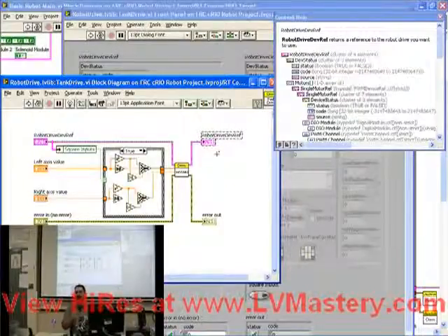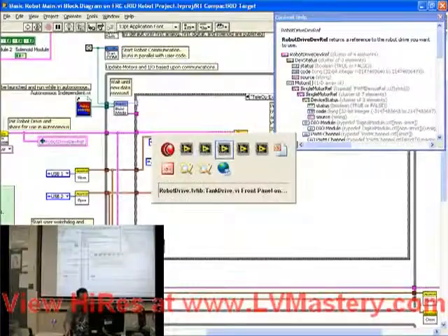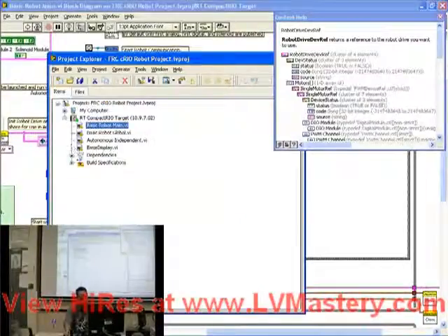Because what will happen, and I wouldn't be surprised if this happens a couple times, is that there will be updated libraries provided by National Instruments and provided by FIRST. This VI is in one of the library sections. So if you update your library, this VI is going to be overwritten. So if you're going to make your own tank drive, your own arcade drive, make a copy of this and make sure it sits in your project. Like I said, I'm just going to get to the project screen, you should only modify the things that are sitting here.